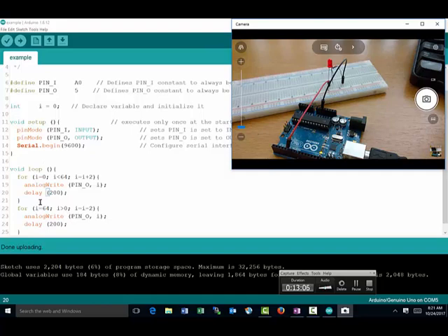So here is a way of giving analog outputs, and even simulated analog works pretty well here. You can use the same technique, as I said, to control anything that depends on power and voltage, to be activated, from heat to light to movement, like motors and things like that. That brings us to the end of another video. This one was focused on analogWrite using pulse width modulation.